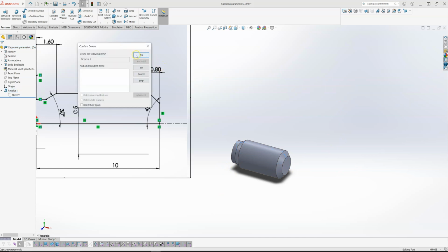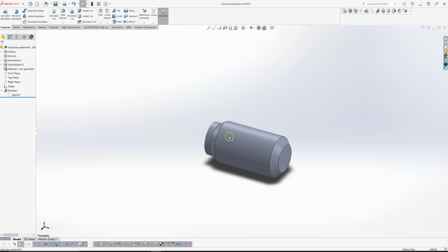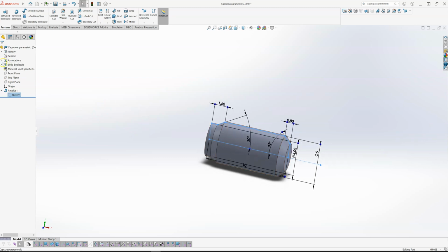Now, just as an exercise for those of you who maybe have this done, if you want to optionally make this a little bit more involved, what you could do is set this up as a parametric model. So this, as I've drawn it here, is an M5 thread. We could set this up in such a way using global variables like we've seen in previous exercises.